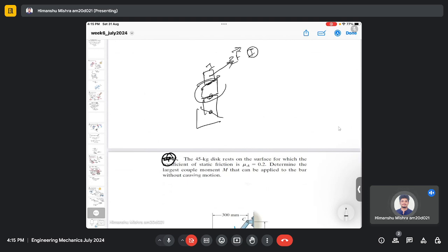Then we only consider block 2, and we do the force balance analysis for block 2. And then we again separately take block 3, and we do the force and moment balance analysis on block 3, and so on. So we actually apply the equilibrium equations on each block separately. This is the usual practice when we solve wedge problems.